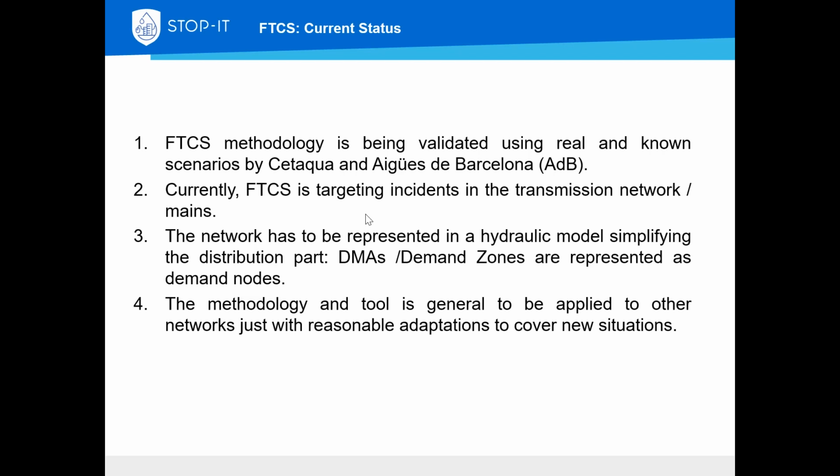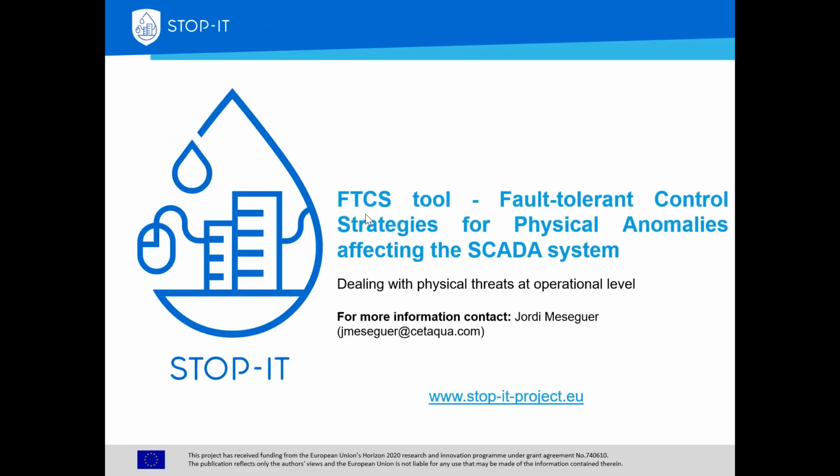The network has to be represented in a hydraulic model, simplifying the distribution part, representing DMAs or demand zones as demand nodes. The methodology and tool is general to be applied to other networks, just with reasonable adaptations to cover new situations.